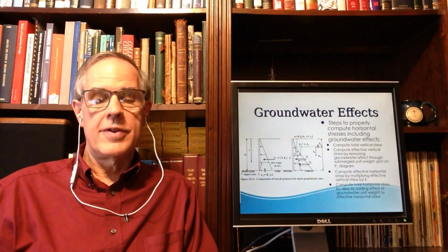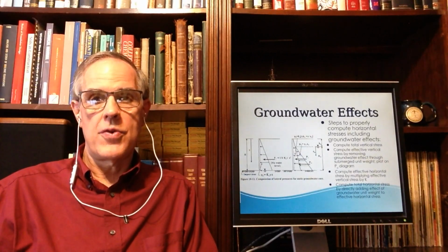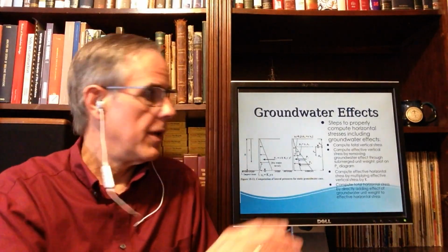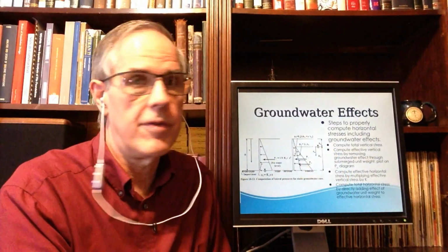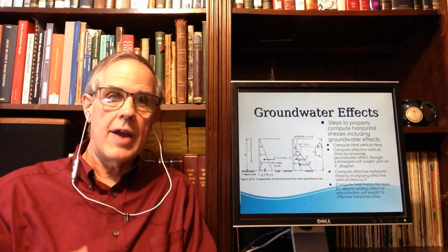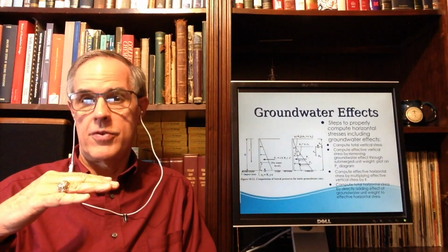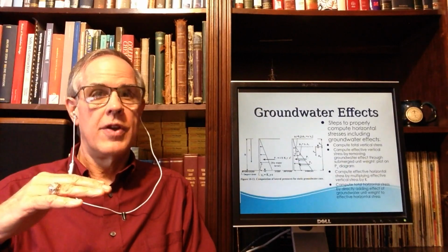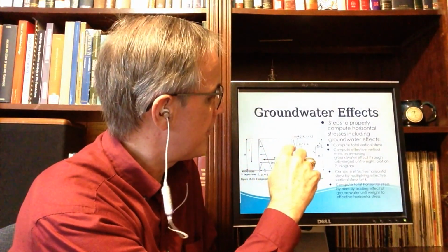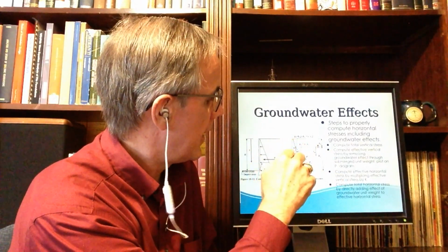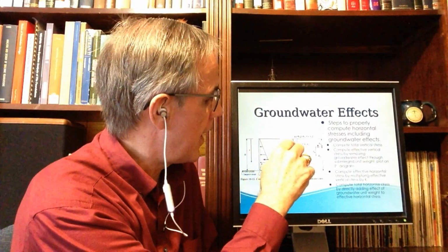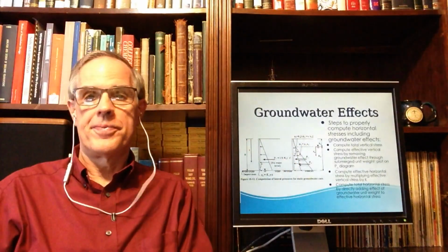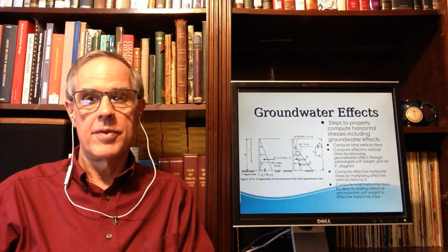The classic example of this, and I bring it up all the time, is tidal forces. If you have a tidal drop between high tide and low tide, and this level is based on high tide, or even if it's just based in the middle between them, you're going to have unbalanced hydrostatic force. Say it's in the middle, for example. Then you're going to be varying with a hydrostatic force. Say this is the level in the middle, and high tide's up here and low tide's down here. At high tide, you've got a net hydrostatic force that's pushing this way, and at low tide, you've got this gap and one pushing that way. Those must be taken into consideration.